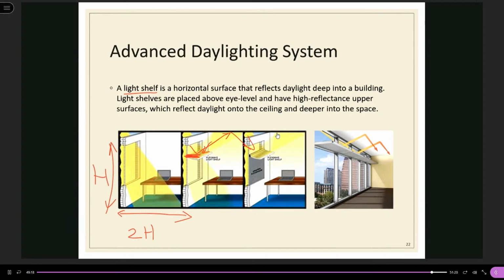For the occupants near the windows, sometimes the sunlight can cause discomfort, maybe due to the glare, maybe due to the heat. Then even when they draw the curtain, daylight can still be emitted into the interior. So the light shelf is a lighting system to allow daylight to enter the deeper part of the interior, so that it can reduce the electrical lighting energy.